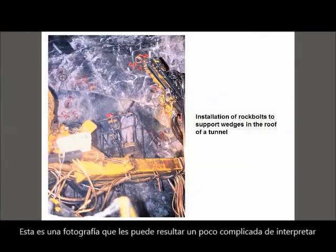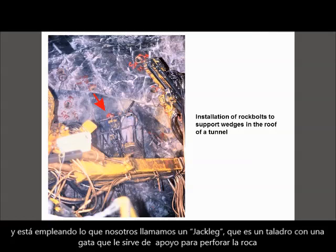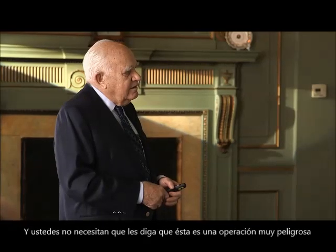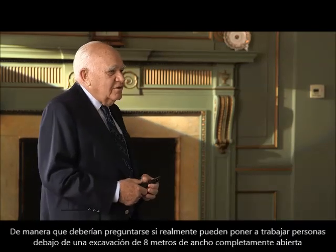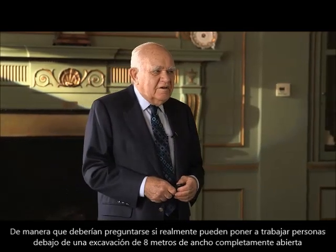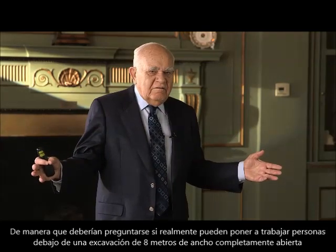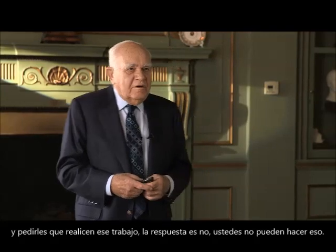This is a photograph which might be a little bit difficult for you to interpret, but you can see a man in the middle of the photograph there drilling a hole for a rock bolt using what we call a jack leg, or a drill with a jack forcing it into the rock. And you don't need me to tell you that's a very dangerous operation. So you come to ask yourself, can I really put people under an 8 meter wide span, fully open, and ask them to do that job? The answer is no, you can't.